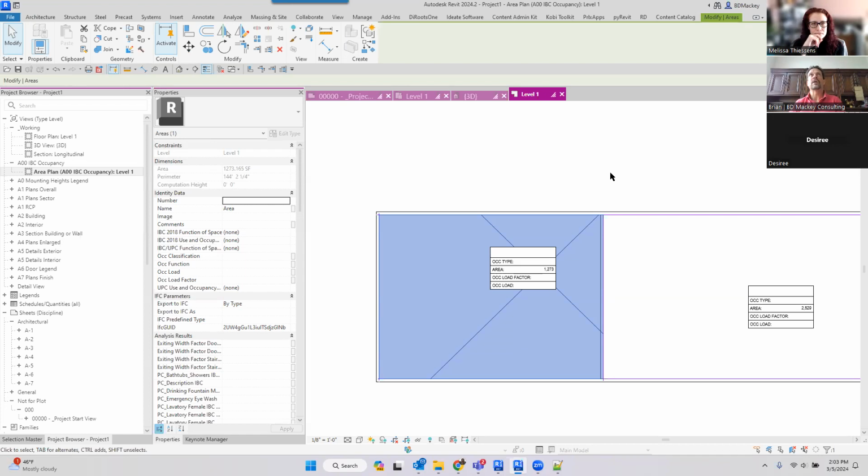The other reason I have a client doing it is they had an old project done in Revit 2020 and they're getting the construction done, and it's almost done, but they're now doing an addition to that project. I think they're adding a whole other wing to the building. So they literally have done Bridge from the old 2020 project into Revit 2024. They just keep publishing over here when things change for RFIs or constructability issues, and now they're getting that Revit file coming in on 2024. It was very interesting to see it do that as well.